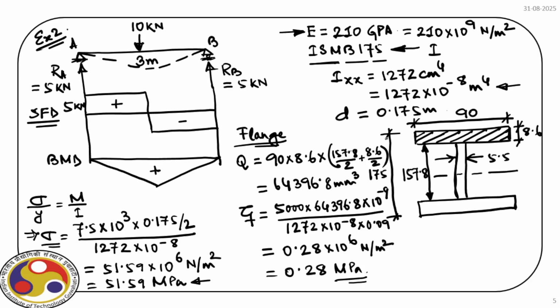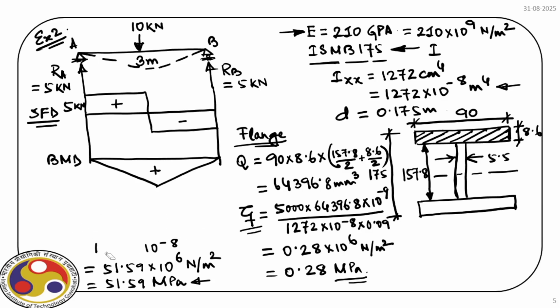If you recall, shear stress at the extreme fiber is 0, and now we have the shear stress at the bottom of the flange. So we'll solve the remaining part in a minute, but before that, let us just mark the cross section and the stress that we have just derived for the flange part, right?